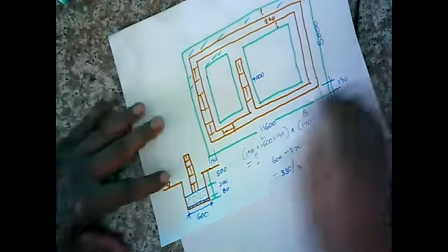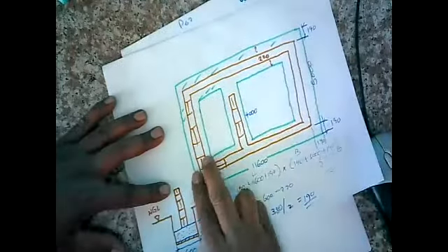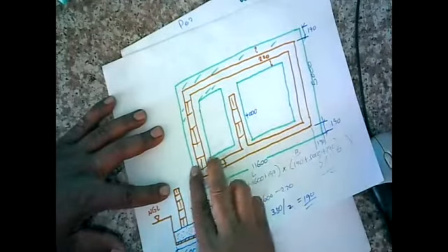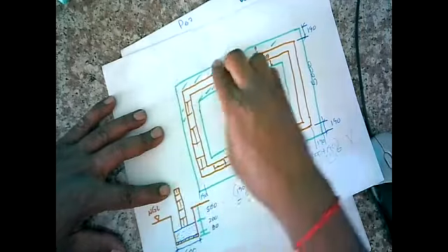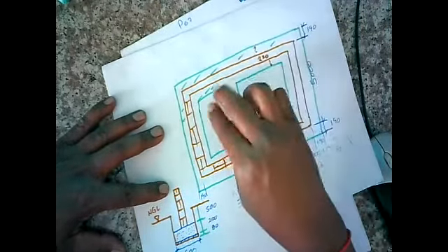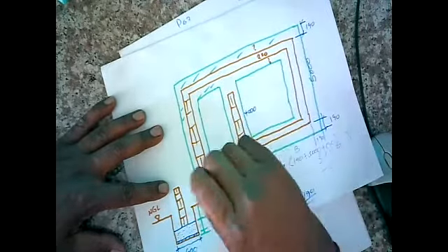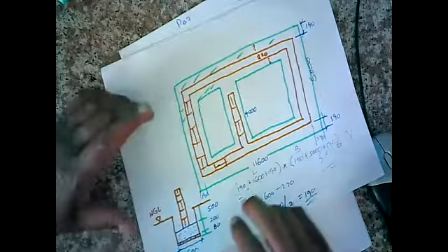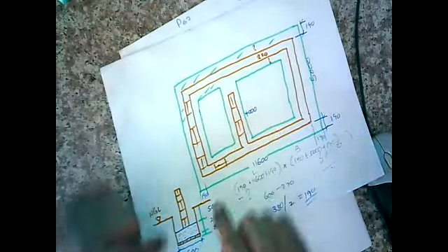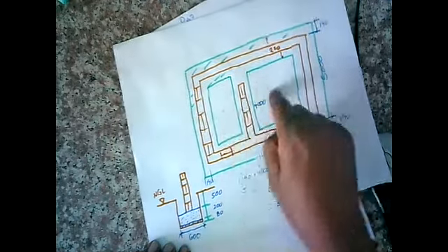Right? So we're going to be digging. Now, we've cleaned this area. We're going to be digging a trench. This is the shape of the trench. We're going to be digging all around here, all around here, all around here. This is going to be standing proud because we're putting a floor on top of it. All right. So we're going to be excavating the dimensions of this here only, not this.